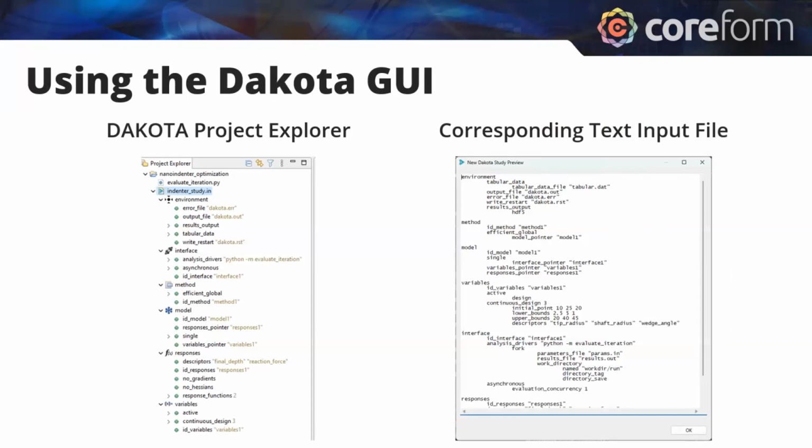Yeah, that is a really good question. So what I would say is DAKOTA is a method at the heart of every optimization problem. You are evaluating objective functions. And those objective functions might be running a simulation to get some values and determine some stress values as maybe a constraint. Maybe I don't want to yield. But if you have one variable, you might write in Python your little bisection method to try to optimize to a solution. DAKOTA handles all of that optimization methodology.